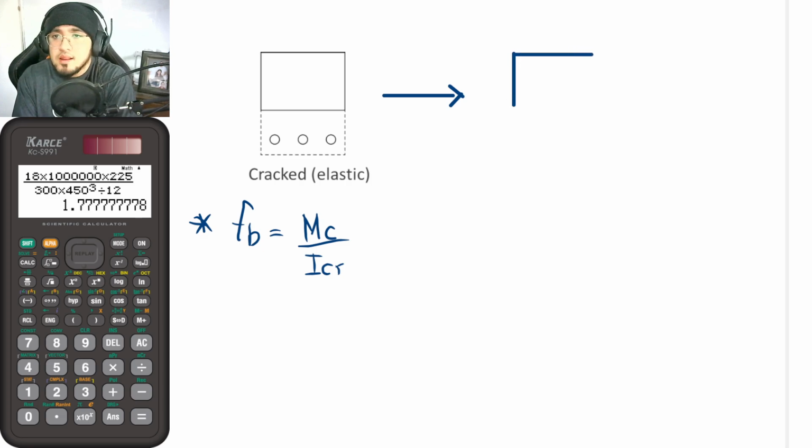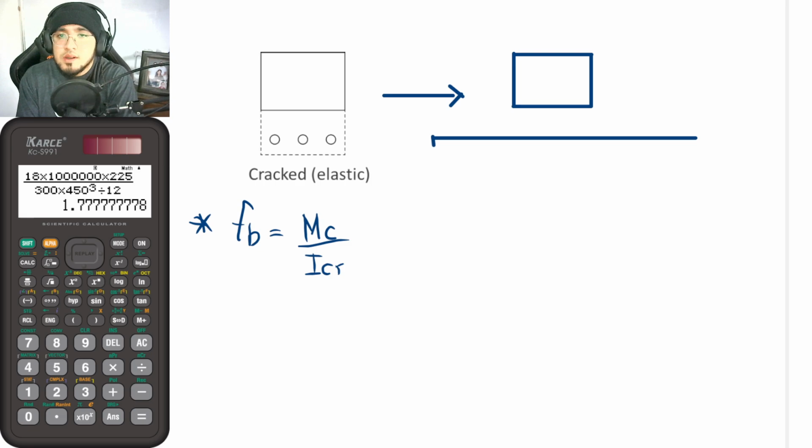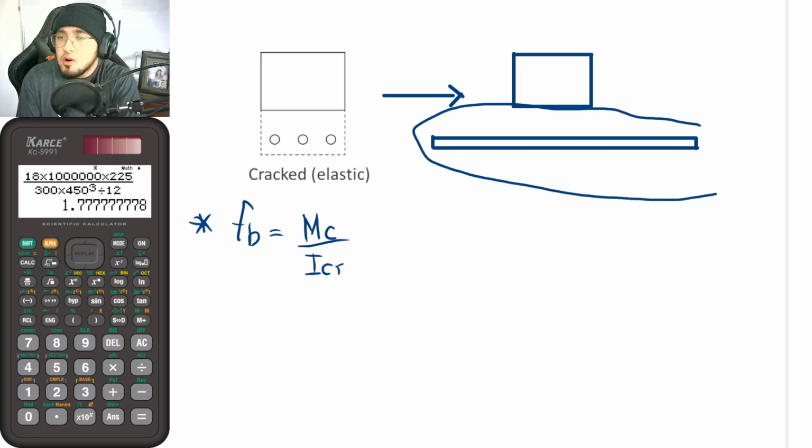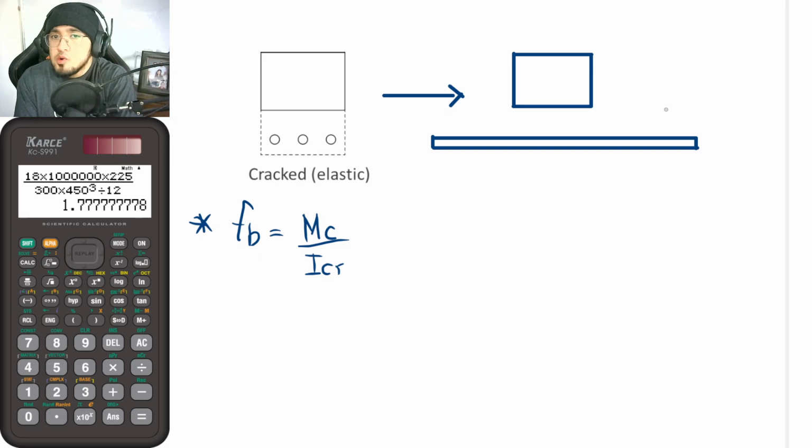This is still the concrete area, and the steel area would now look like this. So this is now the equivalent concrete area for that steel. What is implied here is that it takes this much concrete to replace this much rebars.